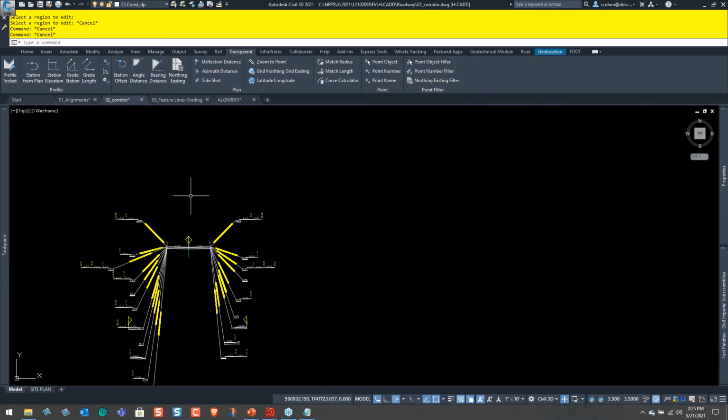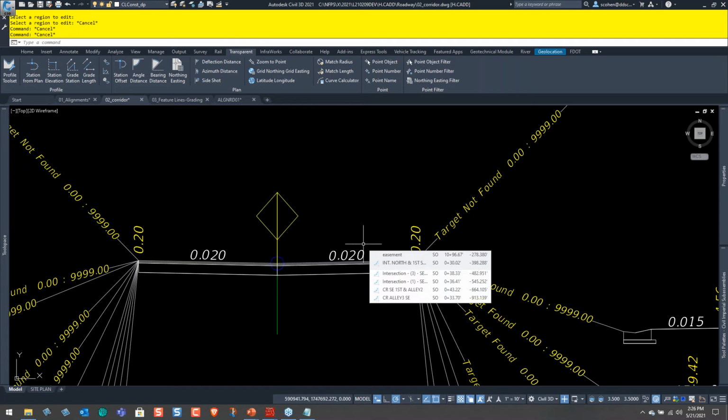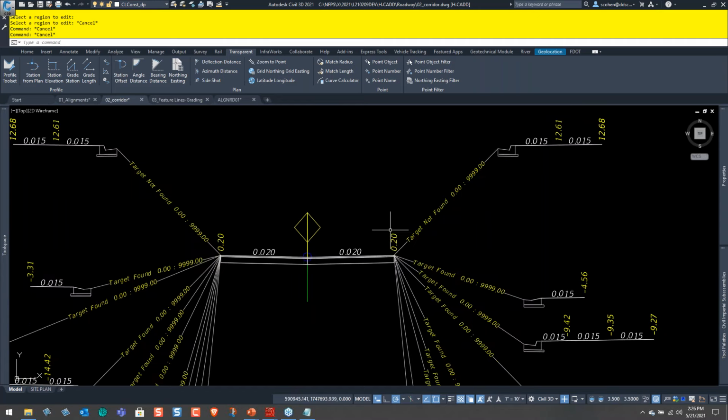So, little tips that I do. This is how I do it. Again, everyone does things differently, and if you have a better way, honestly, just type it in the chat panel. I've seen people do other things, but basically I like to have my targeting options available because I have so many different conditions for this corridor model. I basically started with a default one. It says target not found. What that means is if I don't find a target, it uses this one automatically. It just does it, okay?